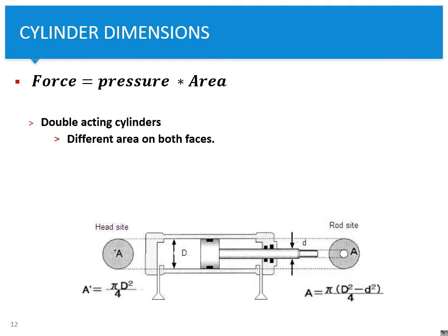There's some solutions to it. For instance, there are double-acting cylinders which have actually a rod on two sides like this. So then, if it's really important to deliver the same force in both strokes, then this can be used. Or you can just choose your cylinder based on the rod side area and diminish the amount of flow or reduce the pressure by some valves or whatever to get a comparable action in the extending and retracting stroke.